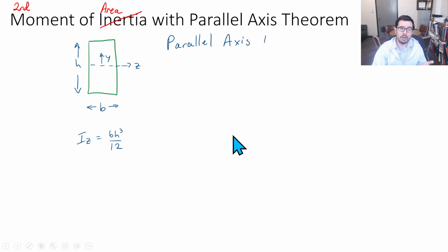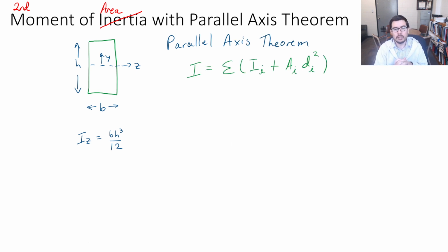Now, you may recall using this previously in some of your physics classes. A lot of times we're thinking of some type of moment of inertia with a mass, and we say it's going to be mL squared or md squared. Since these are areas, we're thinking of second moment of area plus area times distance squared.